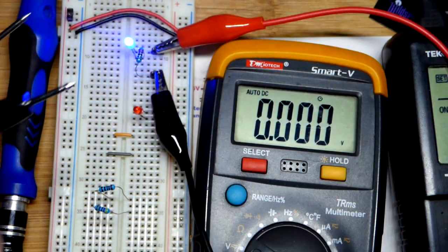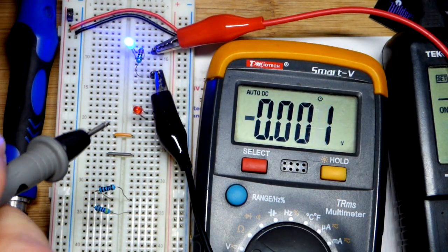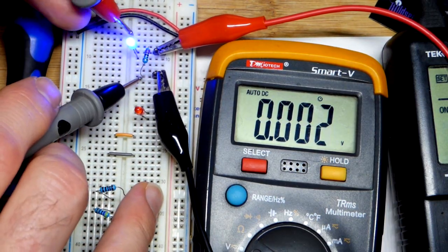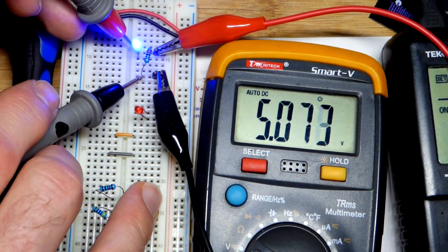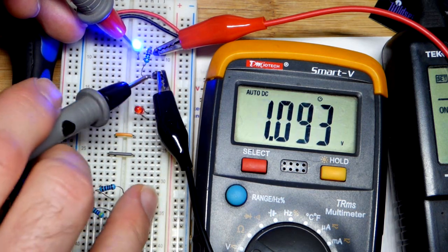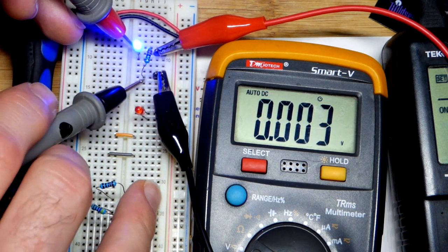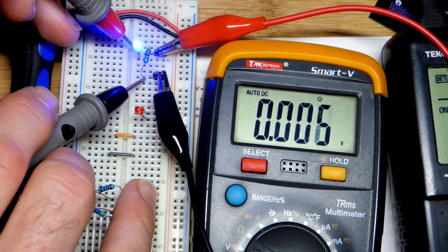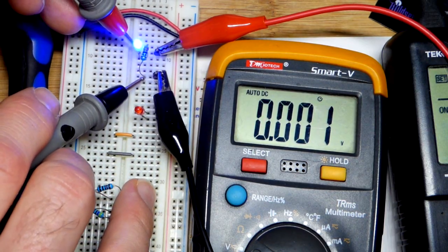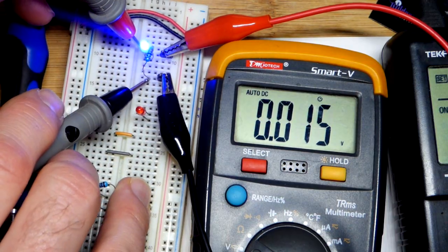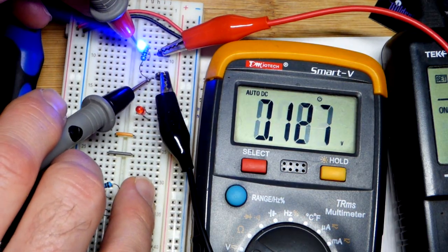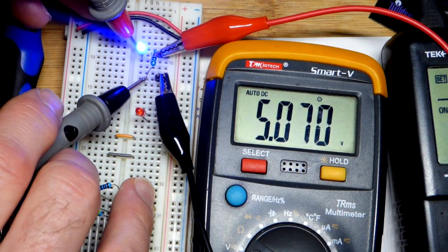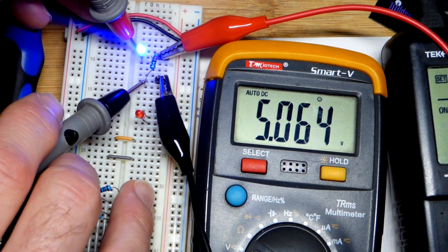So we're powering the circuit right now. So yeah, we can measure again the alligator clips where they clip into the probes or come down here anywhere. That's called a node right there. This is a node. It's all one connection. This side of the resistor, the header pins, and the alligator clip is a node. Same as up there. So I already measured the jumpers across there. Losing a little bit of voltage because this is a cheap breadboard, and connections are not as great as a better one, but still doing okay.